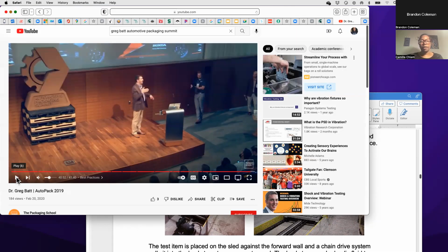Specifically for automotive, like he mentioned about using returnables, the way the polymers perform is different than a corrugated box. So the test that you choose will be different. Corrugated boxes are going to show more fatigue and failure in Florida in the summer, but a plastic returnable is probably going to show more failure in Minnesota in the wintertime.